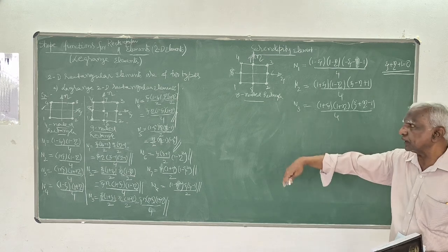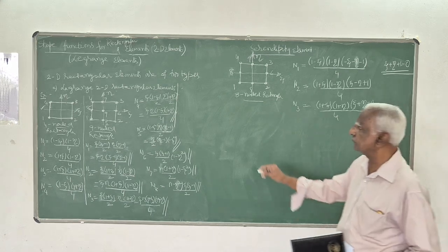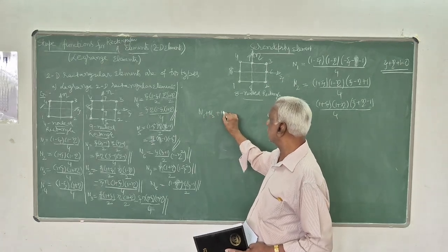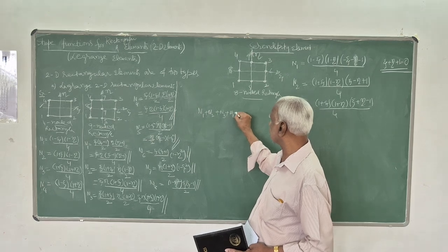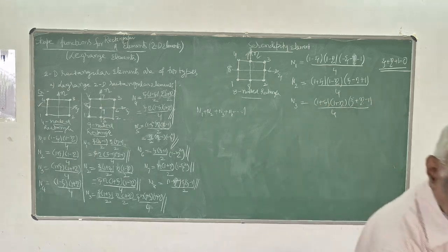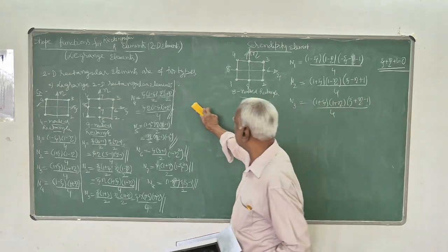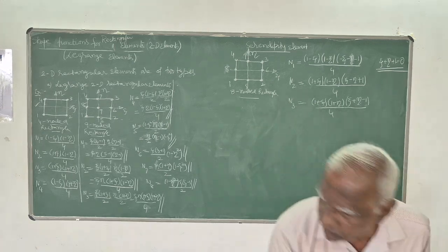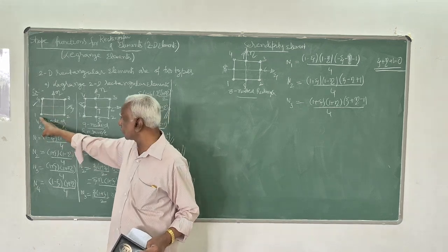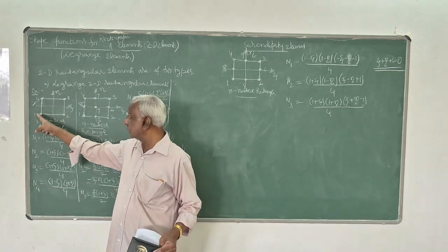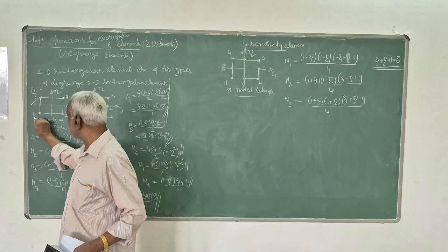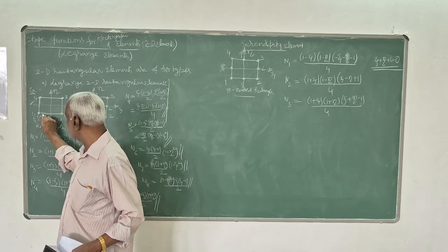Because in all these, the fundamental property of shape functions is that the sum of the shape functions N1, N2, N3, N4 and so on should always be equal to 1. That you can remember. Also, the shape function value at node 1 is 1 when you substitute coordinates. The coordinates of node 1 are minus 1 and minus 1; psi is minus 1, beta also minus 1.